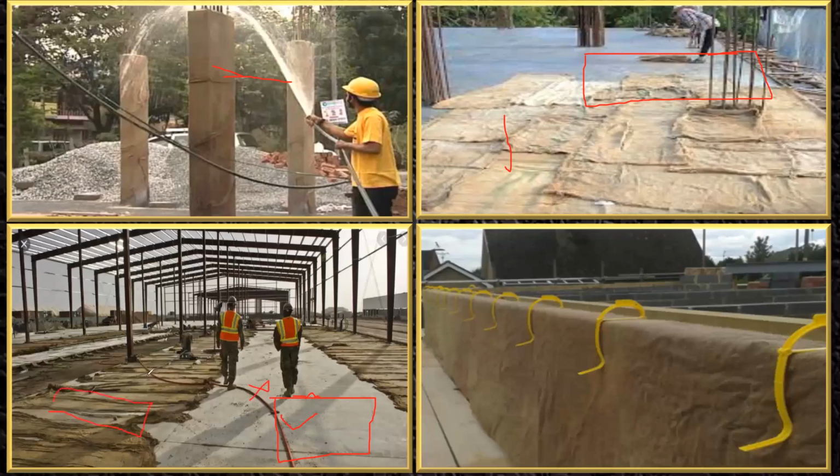This is also okay, especially for an industrial building. These are the steel structures you can see, and this is the vertical element. Let us say they have created a wall, I guess, and this is a kind of holder. When your surface is wet, nothing is going to happen. But when it is dry, what will happen? There are chances that this gunny cloth, due to the movement of the air, may fly out from here. So that is why they have kept a small clip, which will hold the gunny bag in its position, right?